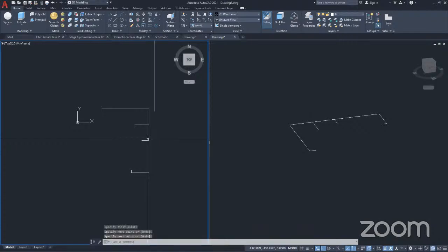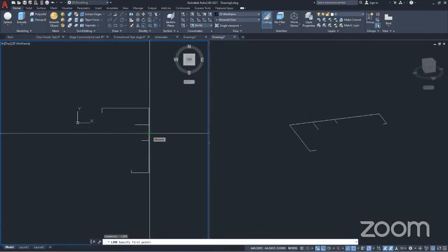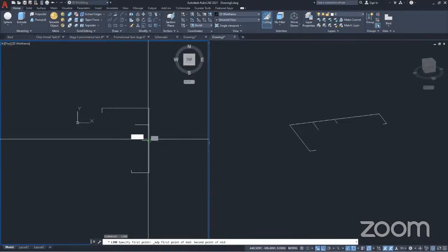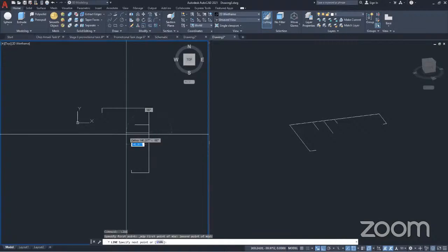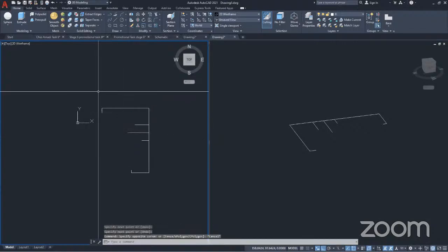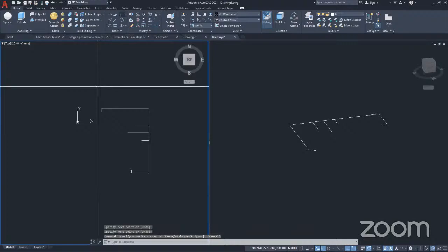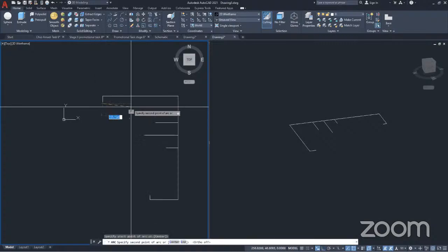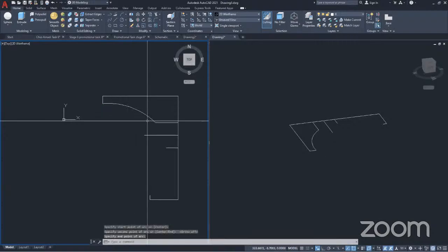And another right here, mid between 2 points. Midpoint between these two. I'll make it out a little like so. Now let me just do something before I do that. I'll use my 3-point arc rather. I'll select here, select 1 point, turn off orthogonal, select 1 point, then select this. I repeat the same thing.